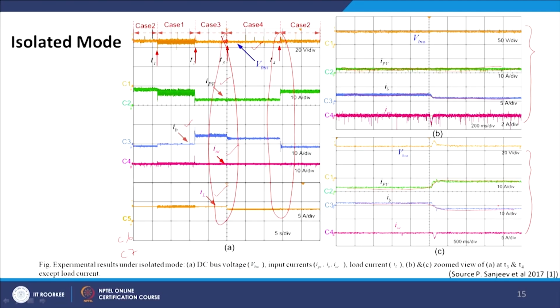And above all, when the grid is not available, the whole energy has to be met within the system, and certainly we have to curtail some of the non-critical loads as and when the battery SOC goes down, and step by step we can curtail the non-critical loads to manage your energy scenario.